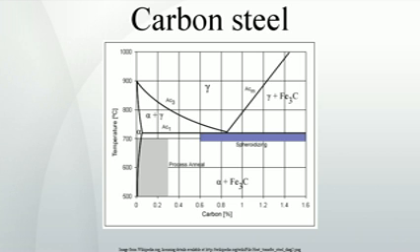Martempering, or marquenching. Martempering is not actually a tempering procedure, hence the term marquenching. It is a form of isothermal heat treatment applied after an initial quench, typically in a molten salt bath at a temperature right above the martensite start temperature. At this temperature, residual stresses within the material are relieved and some bainite may be formed from the retained austenite which did not have time to transform into anything else.